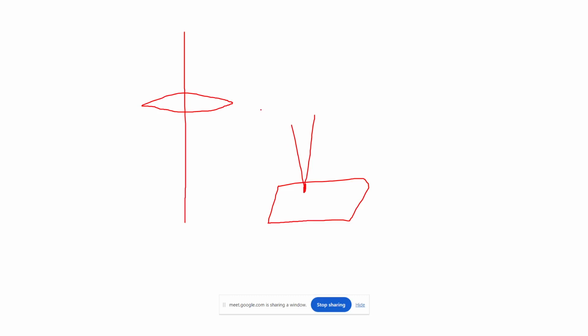So in the SEM we always do demagnification of this probe. The ray diagram is not directly related to object and image, it relates to the probe size. The probe we always need smaller, so in the SEM we always use lenses to demagnify the probe.